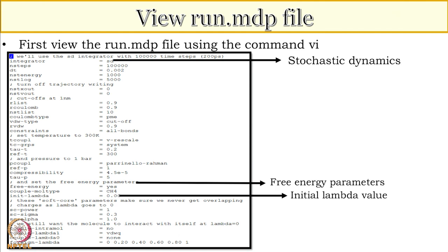If you go to the GROMACS site, it gives you a list of parameters that you can keep for your free energy calculations. So it is already available there. It's written in detail what the parameters are that you will need for an MDP file. You just have to add all these lines at the end of the MDP file that you are already using for your previous calculations. Have they given some examples? Yeah, there are examples given in there. So methane is one example, or are we creating separately? Methane is an example, ethanol is an example. Okay. So there they already have the MDP file.